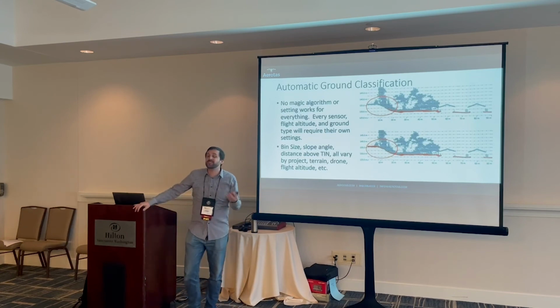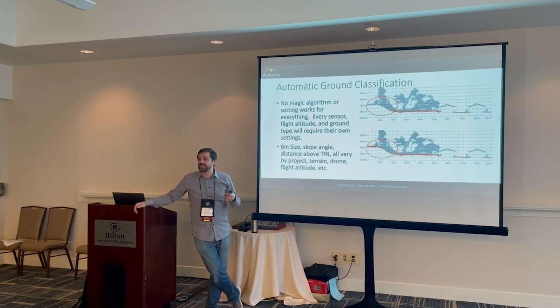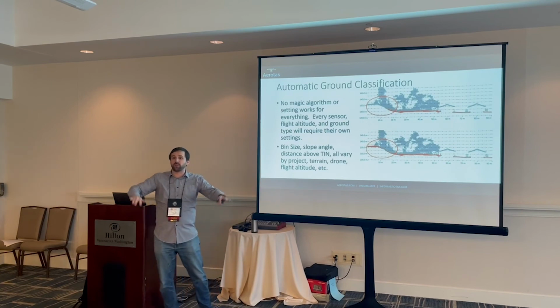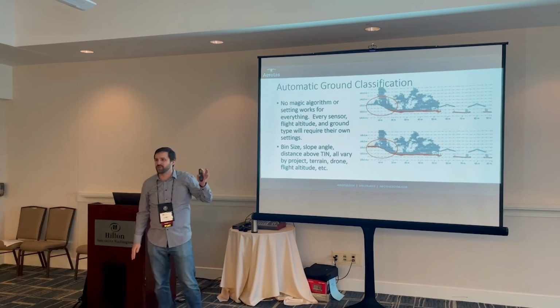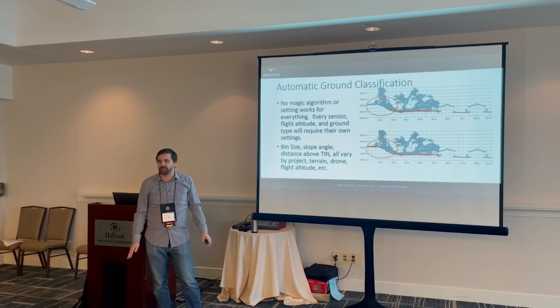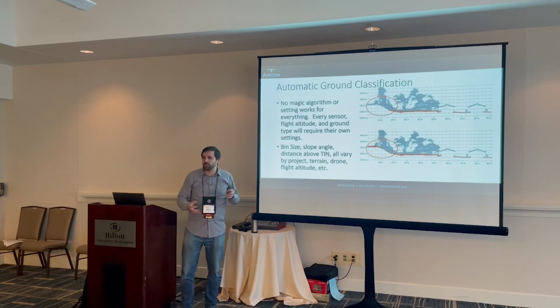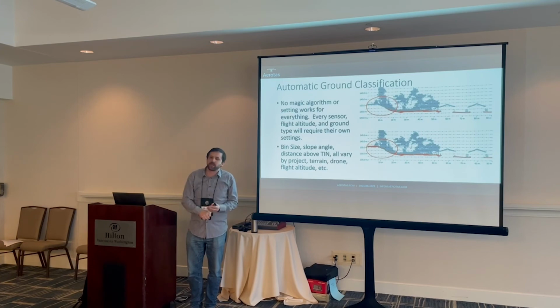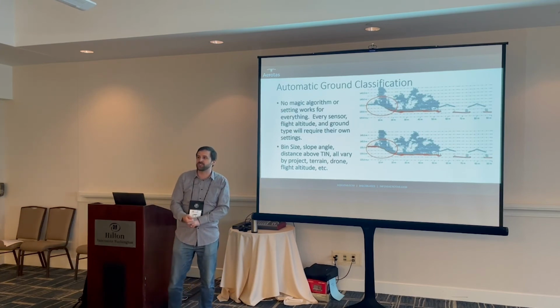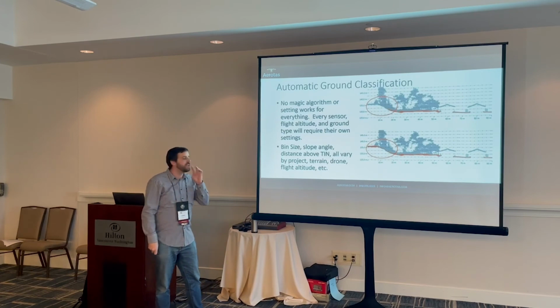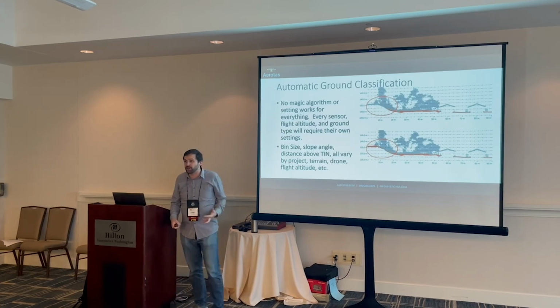context here. So it took a while to get those settings dialed in, and it was very different on that site than on something that is mostly flat with maybe only 5 or 10 feet of true ground elevation change and 100-foot trees. Those will have a way different set of parameters. So realizing, like with Pix4D or any software, it's not about the settings, it's about the workflow. It's about the procedures, that's how you get it. There is no magic set of settings that we've found. There is no AI that is reliable about that.